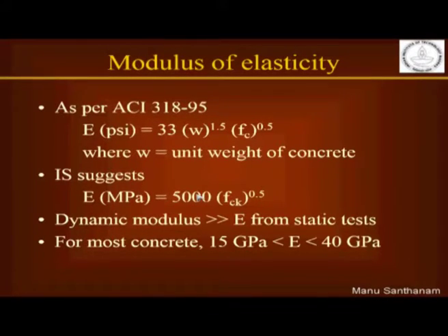Several concretes today with modern materials may or may not satisfy the requirements suggested by this data. So, if you are going to be designing new concrete for a particular building, especially for high rise buildings where modulus is extremely important, it is always better to get the modulus tested rather than rely on this equation, which can go horribly wrong, especially with modern day high strength concretes.